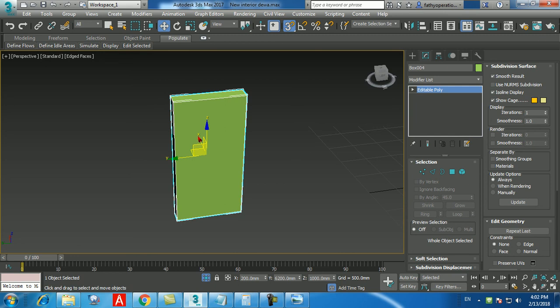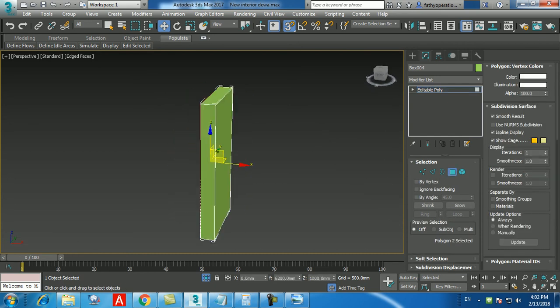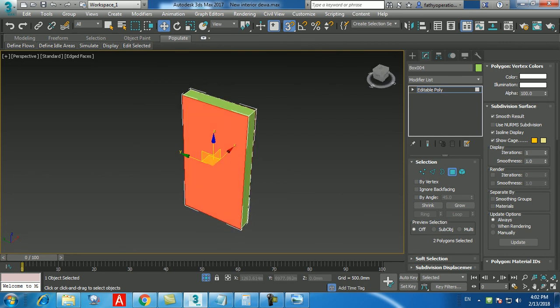So click on the polygon, select the front polygon and the back polygon, both the sides. If I want to do this inset on these 3 faces, then I have to make it separately. You mean that 3 frame? Then you see this frame and this frame, and you will extrude it. Local normal. So you will get a proper frame. Then detach it separately. Okay.